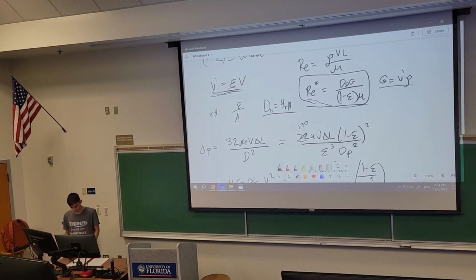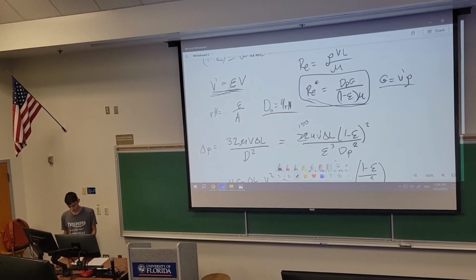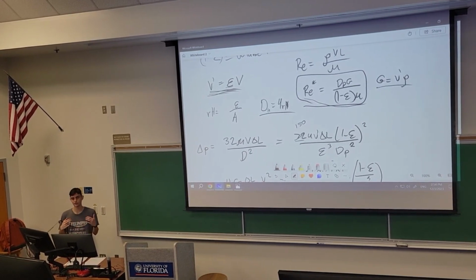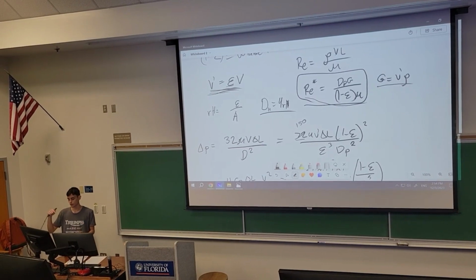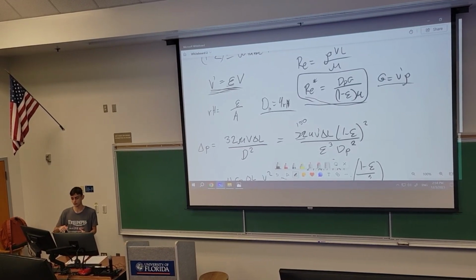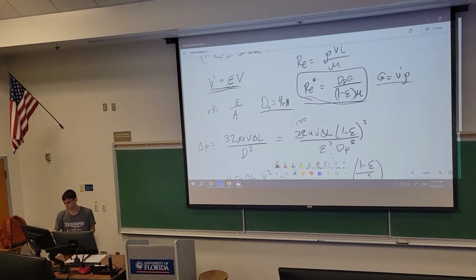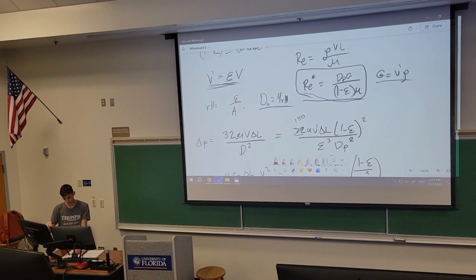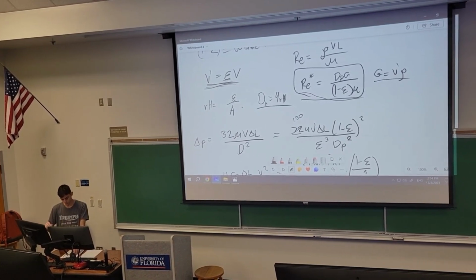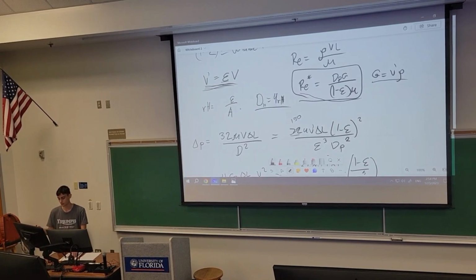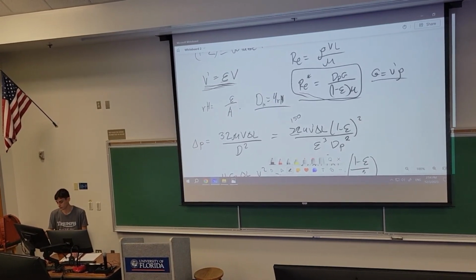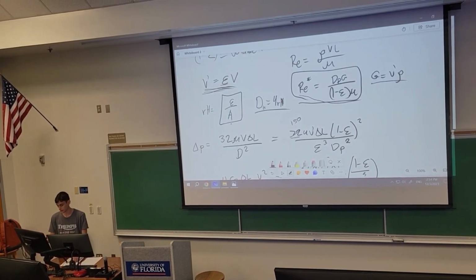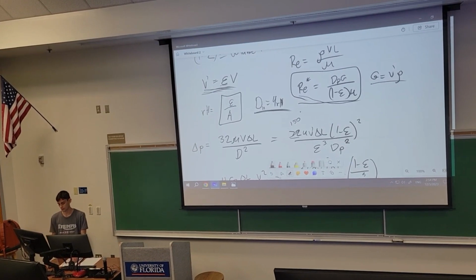All right? Now, let's talk about the hydraulic radius. And this parameter is just a measure of the efficiency of the flow, okay? Because we want the fluid to interact with each of the particles, it measures the cross-sectional area of the available flow over the wetted perimeter, so how much it actually goes into contact with the particles, all right? So we have this here as that relation when we plug everything in and simplify it. And then we also have the diameter, which is 4 times that radius.